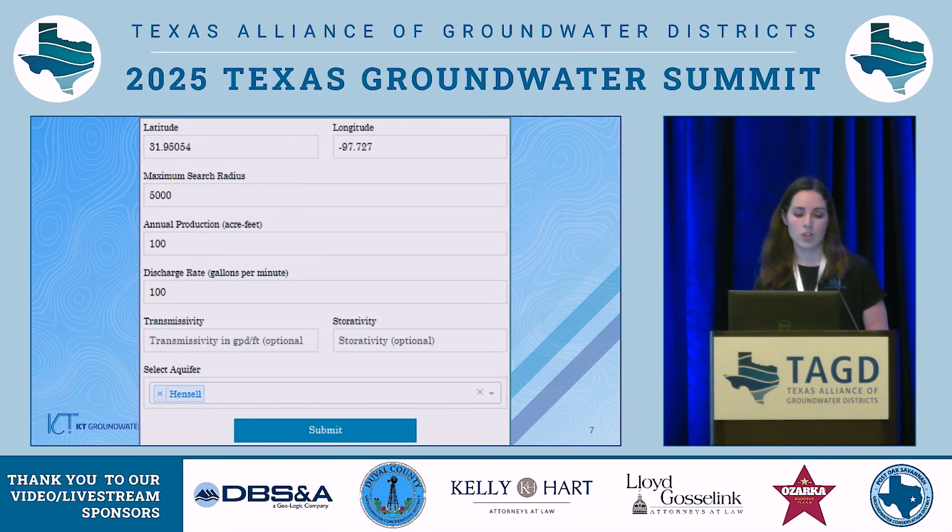In this input section, you'll enter the well location, your maximum search radius, which determines the contours generated around that proposed well. You'll also enter the production rate in acre-feet and discharge rate in gallons per minute. We use both of these values to capture short-term and long-term trends in the aquifer.